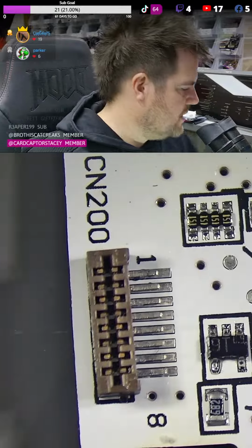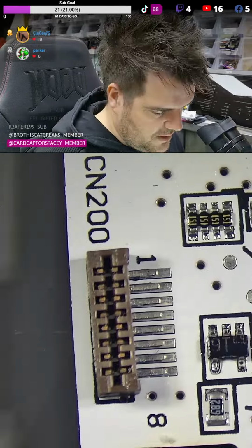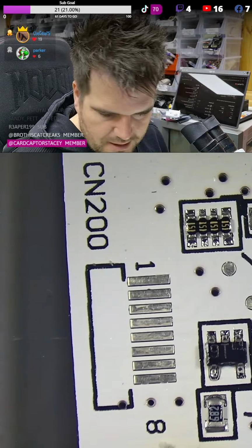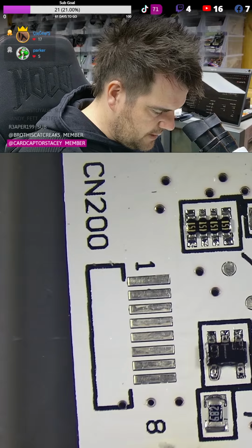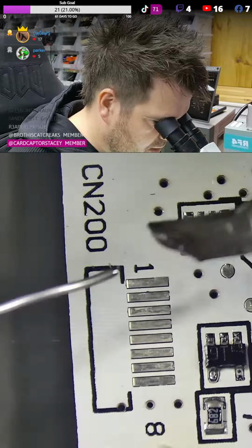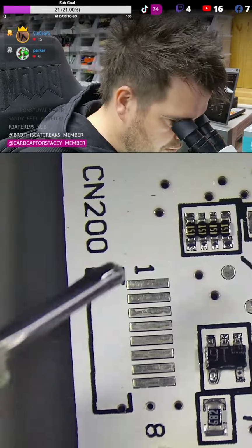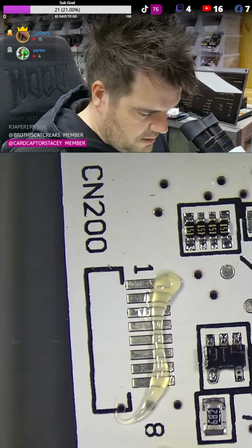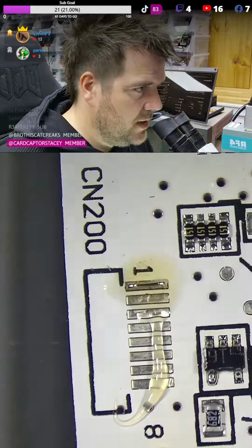This is the first time you guys will have seen me actually soldering with depth perception. This is something you don't see me doing, because I have to solder from a top-down camera with massive delay. We still manage. I'm going to put this fan on now as well. I keep saying I really need to get this fume extraction stuff sorted, otherwise I'll have really bad throat. So I'm just going to clean the tip of the iron first. Then I'm going to put flux on. And we'll probably need more of that. But I'm going to pre-tin just one pad, so try your best to just tin one pad, like so.